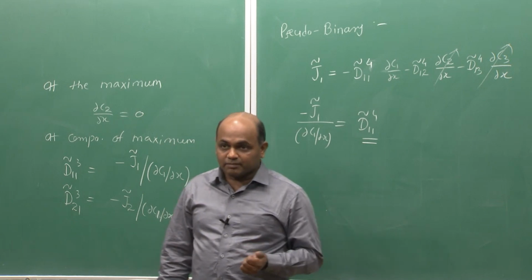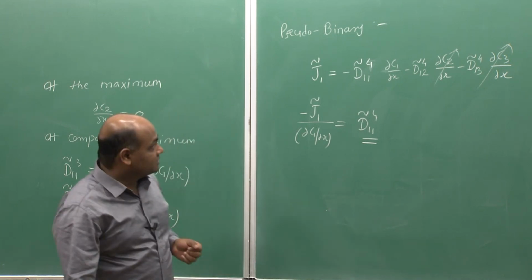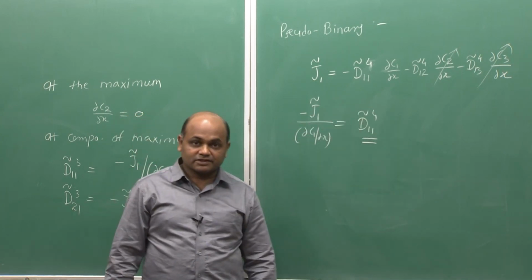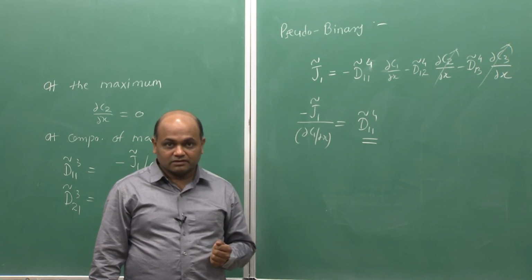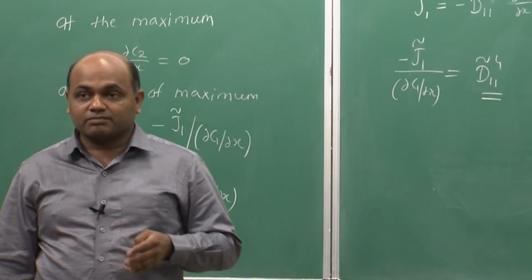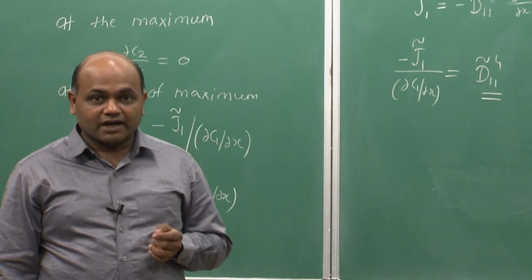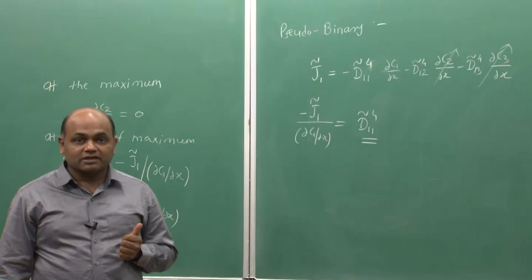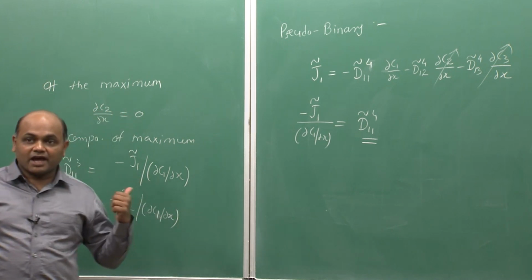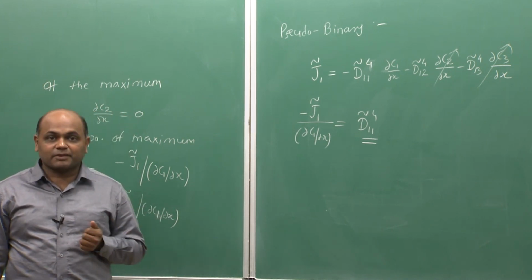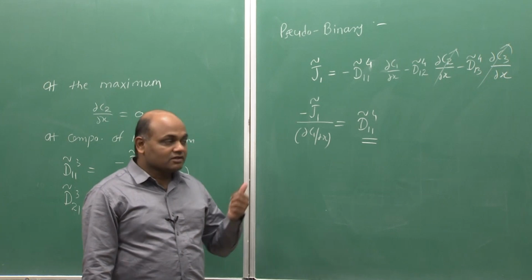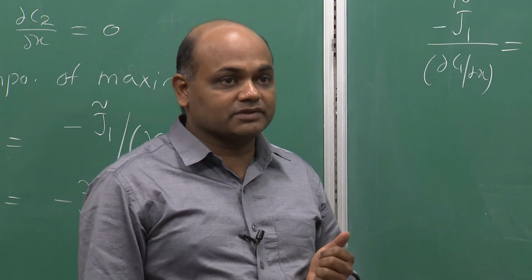Similarly, a pseudo-ternary approach has also been proposed, in which instead of 2 here we will have 3 varying concentrations and remaining constant. And if we can design 2 such couples with the same set of components which being invariant and having at least one common composition in the diffusion zones of the 2 couples, similar to the Kirkcaldy's approach for ternary that I explained, we can solve the 4 equations at the common composition and get 4 independent interdiffusion coefficients.